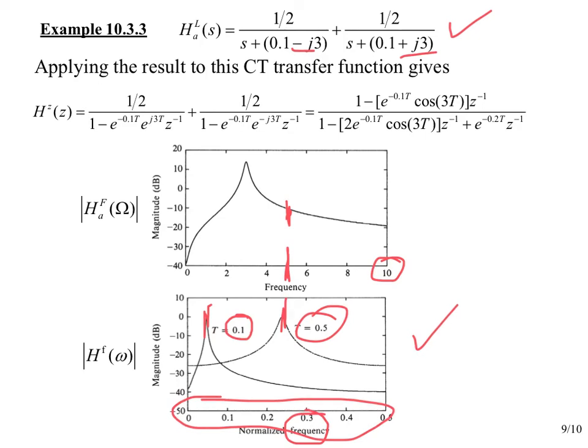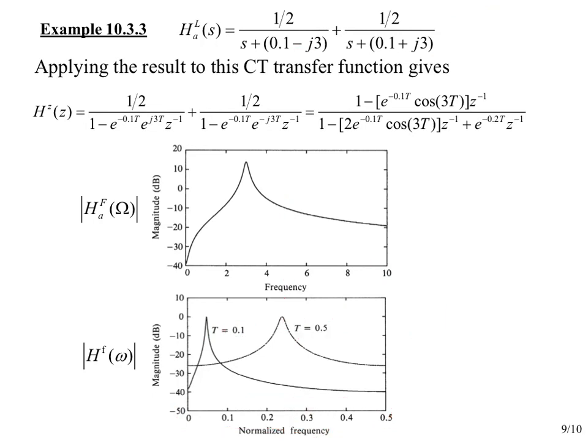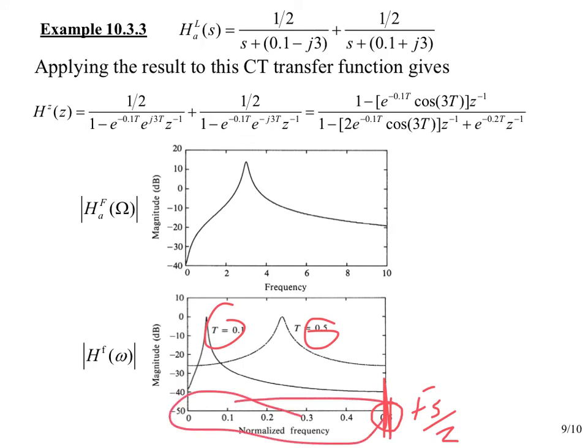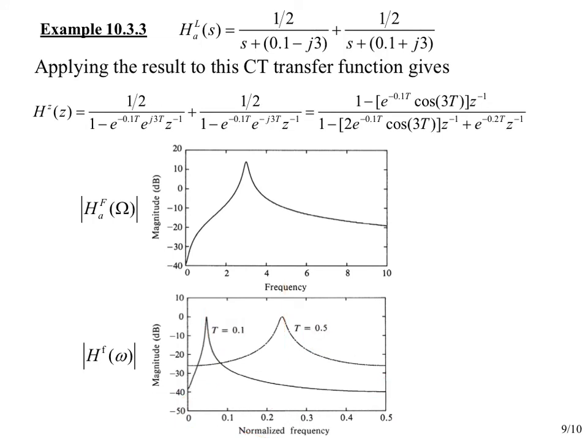We know that when we do the mapping from discrete time to continuous time, this is normalized frequency, so this corresponds to pi. That's going to map to Fs over 2. So for different Fs over 2s, how this frequency maps to physical frequencies changes. And so all of these will get mapped to different physical frequencies. That's why these spikes are in different locations for different sampling rates. But more importantly, we see that the basic shape of this changes quite drastically.